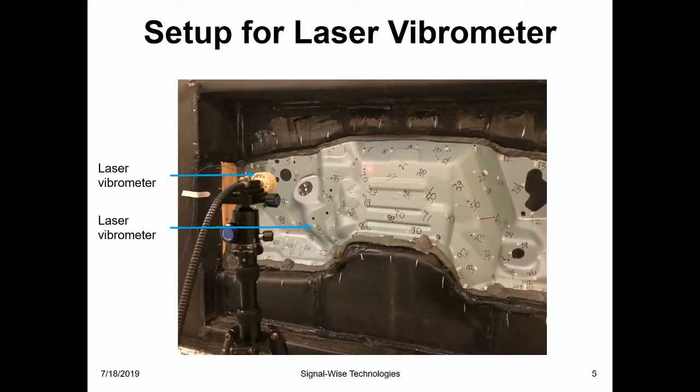Tests were conducted in a typical industry setting using a coupled semi-anechoic chamber and a fully reverberation chamber. The truck dash panel was mounted on a wall through a fixture that separated the semi-anechoic chamber and a fully reverberation chamber. A laser vibrometer was used to measure the normal surface velocities at some discrete points that were accessible to a laser beam.